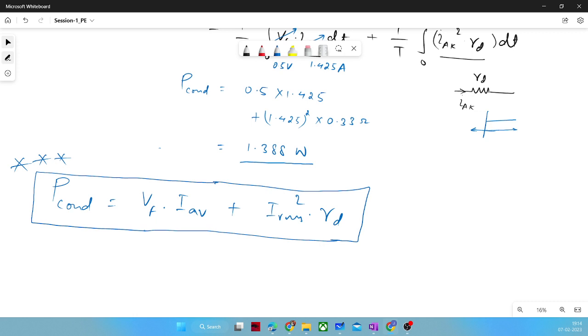To get that outcome, we switch it so many times, turning on and off, so its frequency will be higher, and power loss is directly proportional to frequency. So if you are switching at such a high frequency, your losses will be higher. I hope this is justifiable.